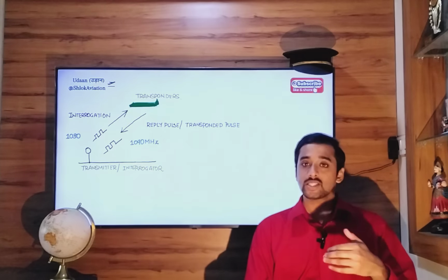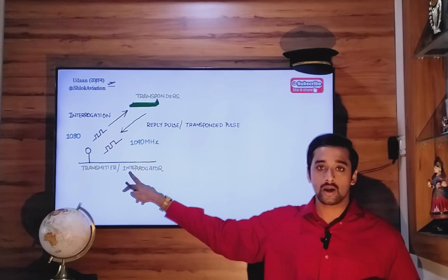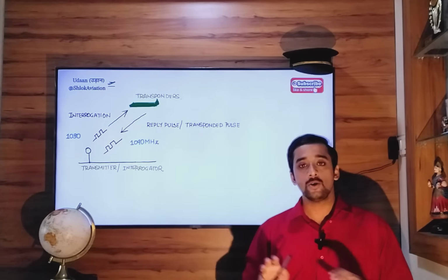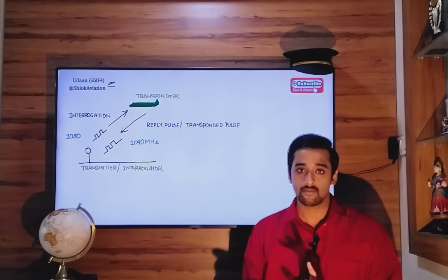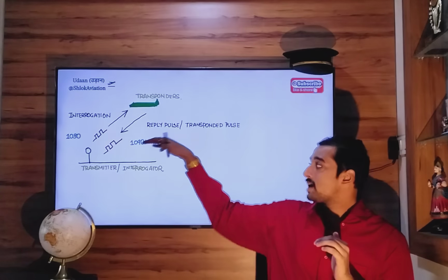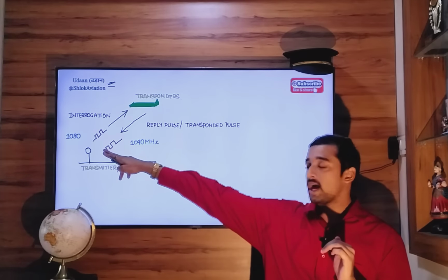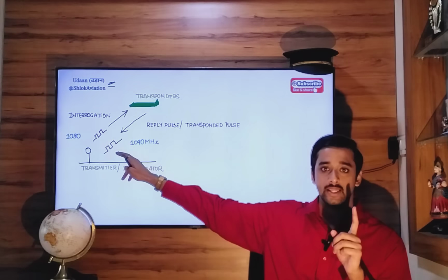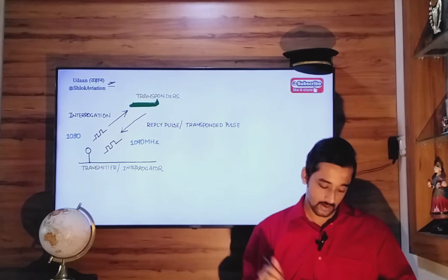Now, a ground station can also be a transponder. Aircraft can also be an interrogator. Okay, so irrespective of their roles, the frequencies at which they transmit are going to remain the same. Aircraft is higher, it flies at a higher level than the ground. So the number that belongs to it will be also higher than 1030. Remember like that. So ground 1030, this is 1090 by aircraft.